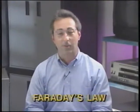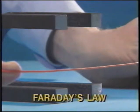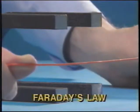These four factors are related to a basic law of electromagnetic induction, known as Faraday's law. This law states that the voltage induced in a conductor is directly proportional to the speed at which the conductor cuts the magnetic lines of force. This law is the basis for the design of the electric generators in use today. Let's take a closer look at how a generator works.